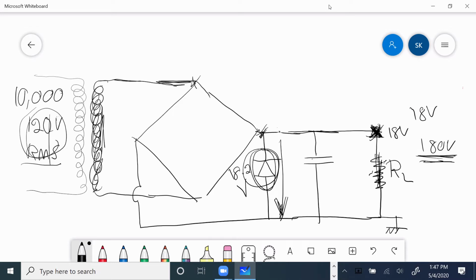Mister, I got one question. In theory, this seems neat, but in practice, a Zener diode like that wouldn't necessarily protect your electronics, right? Since the ranges of lightning are probably in the millions of volts, I don't think the Zener diode will necessarily protect everything, so to speak. Because we observed in real life that, especially if it happens relatively close, it's going to fry anything that's plugged into the mains.